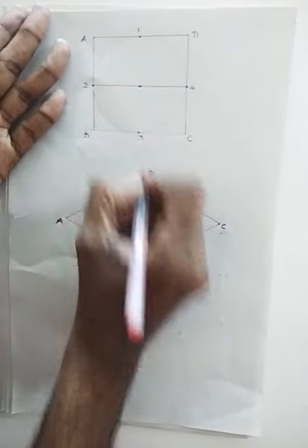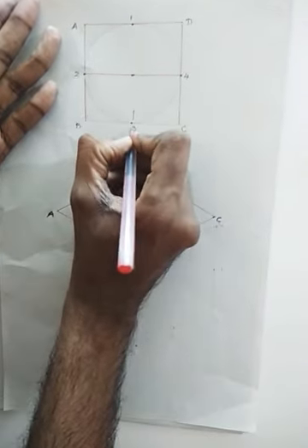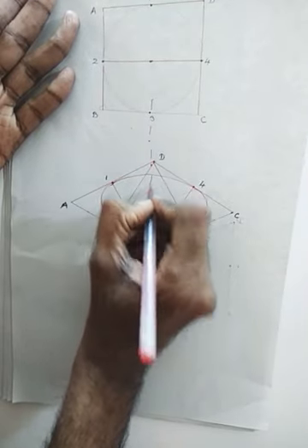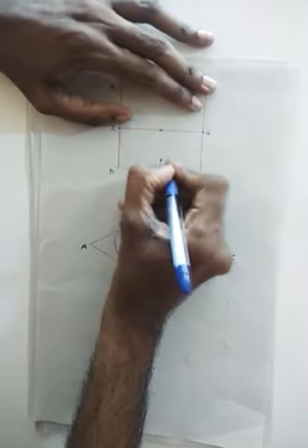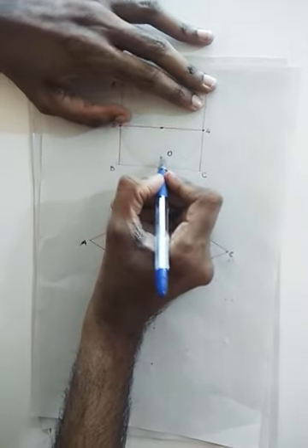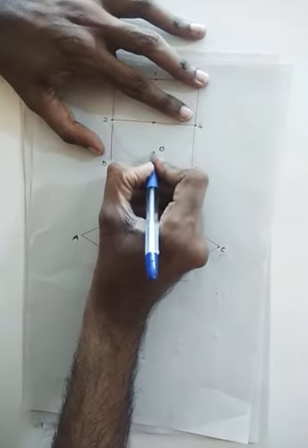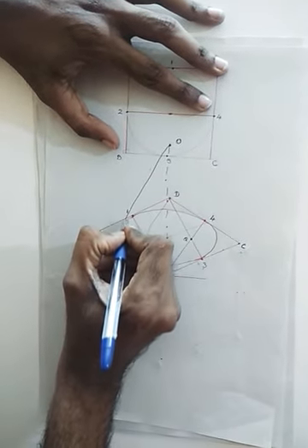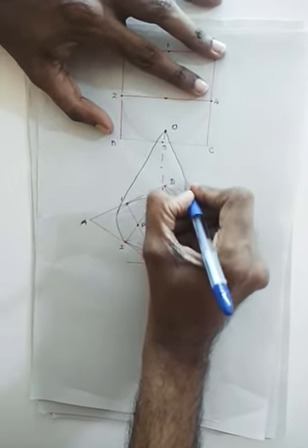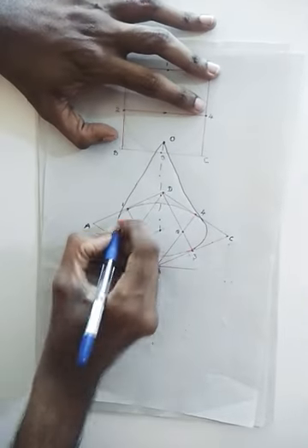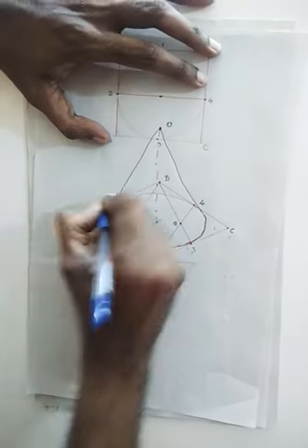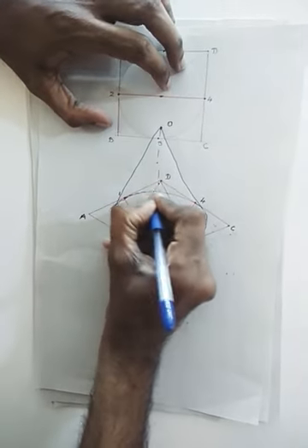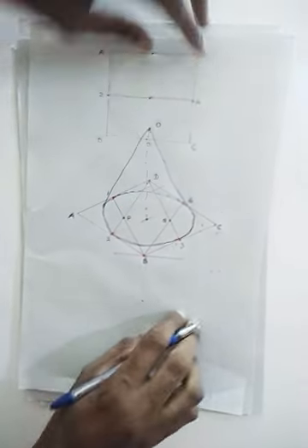We are drawing a cone. So first, from this point, you draw the axis of the cone. Axis is given as 80 mm, so you have to take that dimension from isoscale. I will be getting the apex here. This will be our apex O. Now you draw a line from O tangential to this ellipse on both sides, a line tangential on this side, a line tangential on this side. We will be getting our cone. This portion should be made dark, and the portion that is inside our tangential lines should be dotted. So this is how our cone will look.